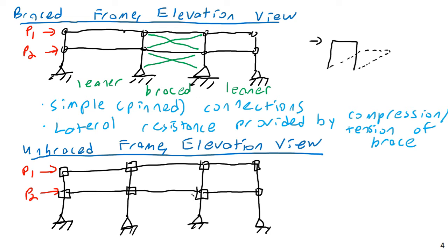So, what I mean when I say resist rotation, I don't mean that they're going to resist rotation. They're going to resist relative rotation. So, if I have an arrangement like this before load is applied, after load is applied, maybe exaggerated of course, they're going to look something like this. So I had previously had columns coming in here and beams coming in here. After force is applied, they're going to look something like this.